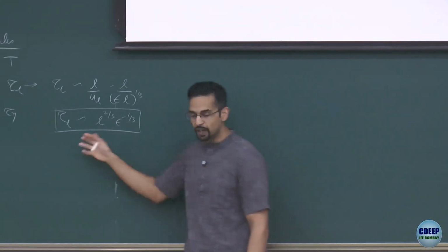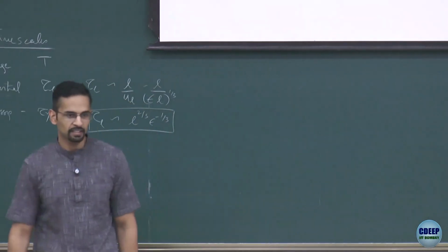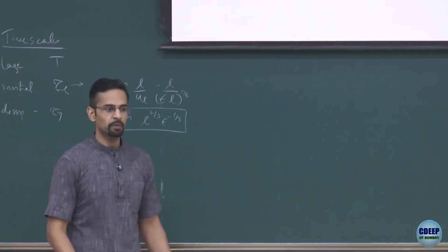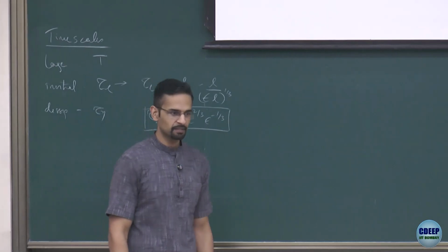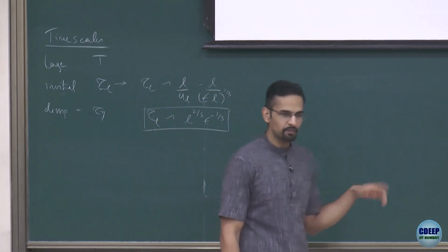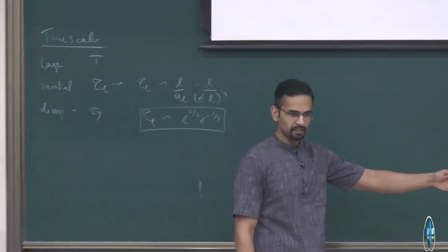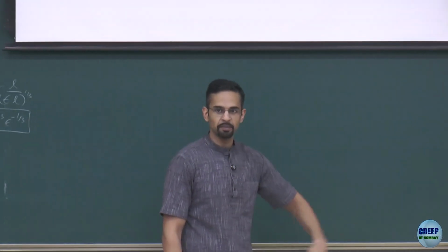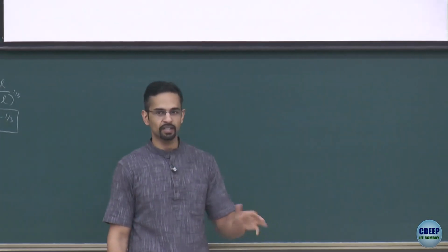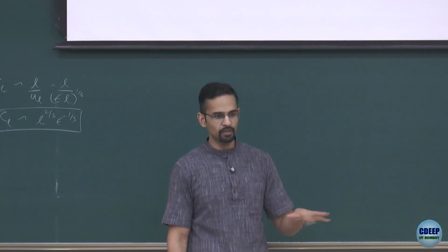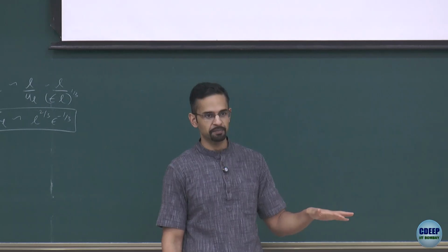Okay? So this fact means that in the inertial range, I should be able to get a power spectra. Okay, so I just showed you the previous time we had an energy spectra. That was a spectra in Fourier modes in space, right, at different wave numbers k. But when we typically think of doing Fourier transform for a periodic signal, we're talking about the power spectra that is in time.